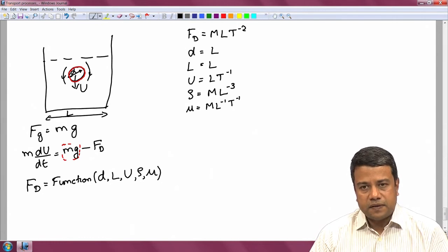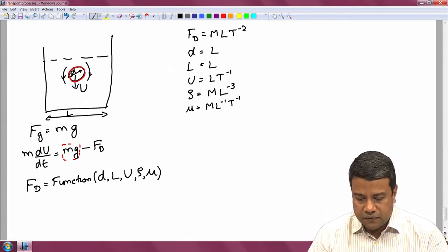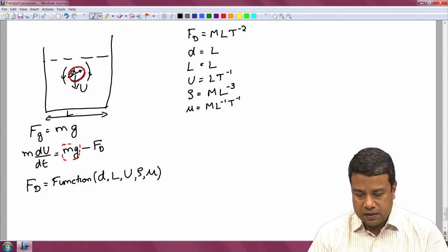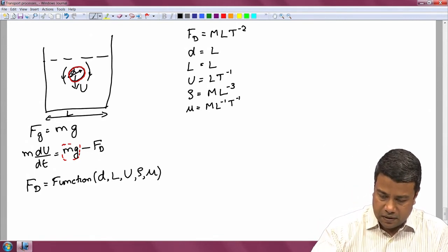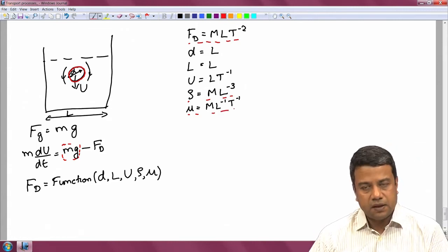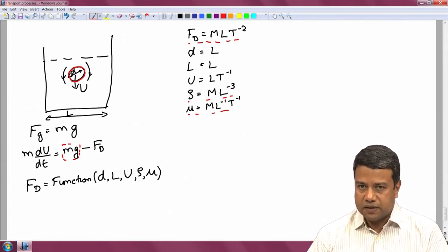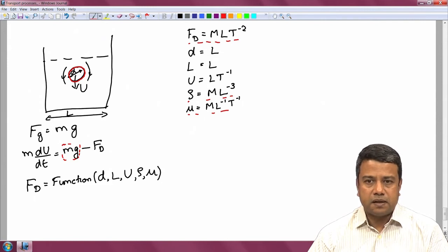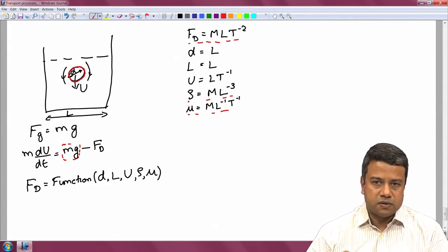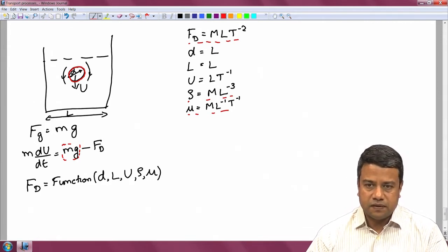So, how do we get the dependent dimensionless group? For that I have to scale the force, which has a mass dimension in it, with either the density or the viscosity, combined with the velocity and the length scale. I can choose either of these, both are valid choices. I will come back and tell you in which cases we should choose the density and in which cases we should choose the viscosity. But at this stage both of these are valid choices.